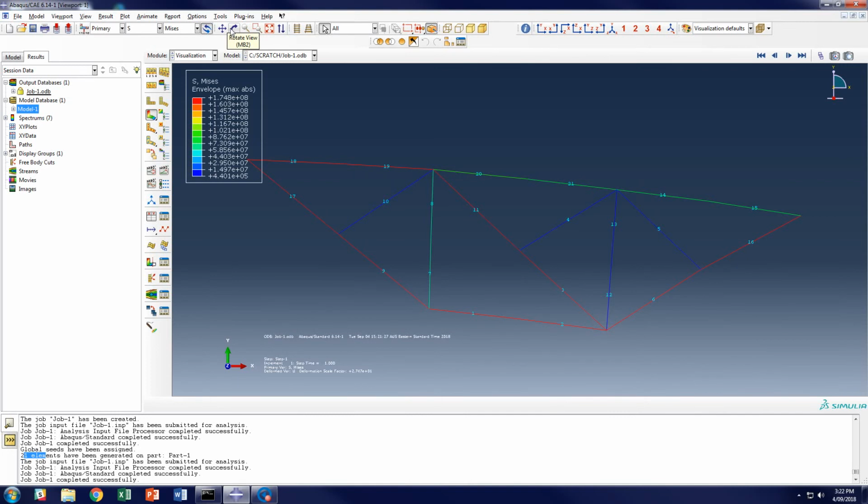So a difference of 5 megapascals may mean that we need to continue to reduce the size of the elements, that is, increase the number of elements in our system. So changing from 169 to 175 could be considered a significant change in stress for the purposes of making engineering decisions. If the change was maybe 0.2 megapascals, then potentially that doesn't change my engineering assessment of the system.